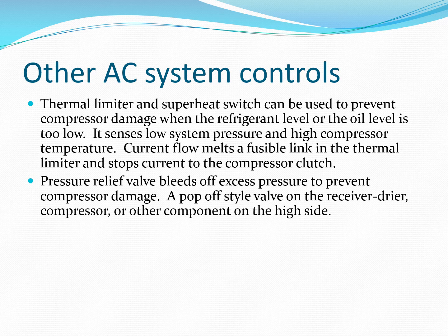A pressure relief valve bleeds off excess pressure to prevent compressor damage. We don't see too much of this anymore because we don't want to bleed off refrigerant into the atmosphere. But in years past, we did have a pop-off style valve on the receiver dryer or the compressor or some component on the high side of the system to bleed off excess pressure. We don't see this too much anymore.